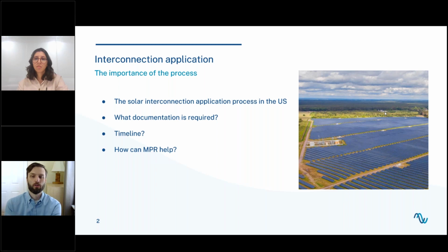Additionally, NERC, the North American Electric Reliability Corporation, is also promulgating new rules that are also driving increase in documentation, especially in simulation and modeling. So you have several trends that are driving an increase in documentation when a developer submits a new interconnection application. Some of this documentation you get from the inverter manufacturer, such as harmonic distortion, short circuit contribution. Others of it, such as the modeling and simulation, need to be created.